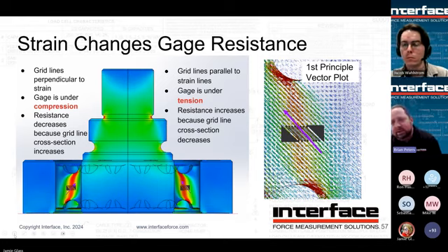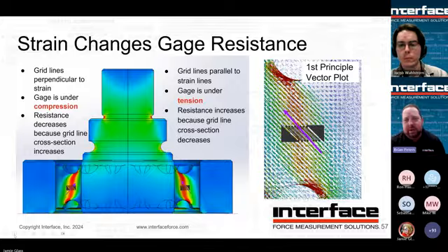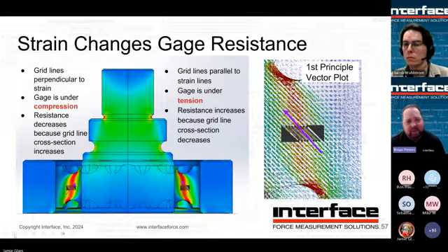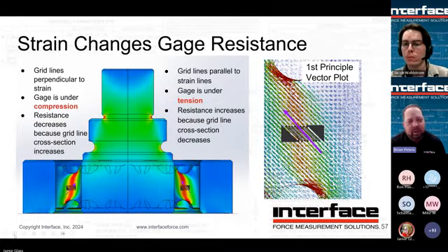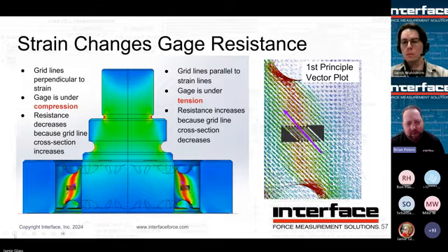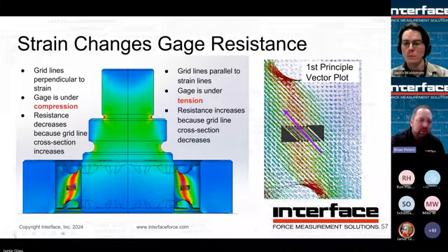Now, our 1800 series takes it one step further and is what is depicted here, and it's a feature we call an integrated stud, where it's all part of the same machined element. And we do this for some of our more demanding applications, some customers that really want the best performance. We'll do an integral stud. So it's all one machined element, and it completely eliminates the chance of any variability there in terms of how that force is introduced much further away from the gauges and then propagates down through consistently every time to where the bridge is.